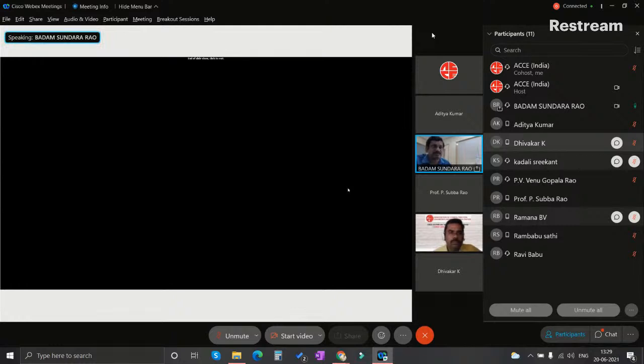The peculiarity of sands is that with depth there is definitely an improvement in the modulus, and you have an increase in the N values, from the density point of view. Also, you have extraordinary variations there. It will change its state at least from loose to medium dense, or from medium dense to dense. That case also we have observed. That is a peculiarity, and one of the characteristic conditions is the behavioral change in the densification of the soils.